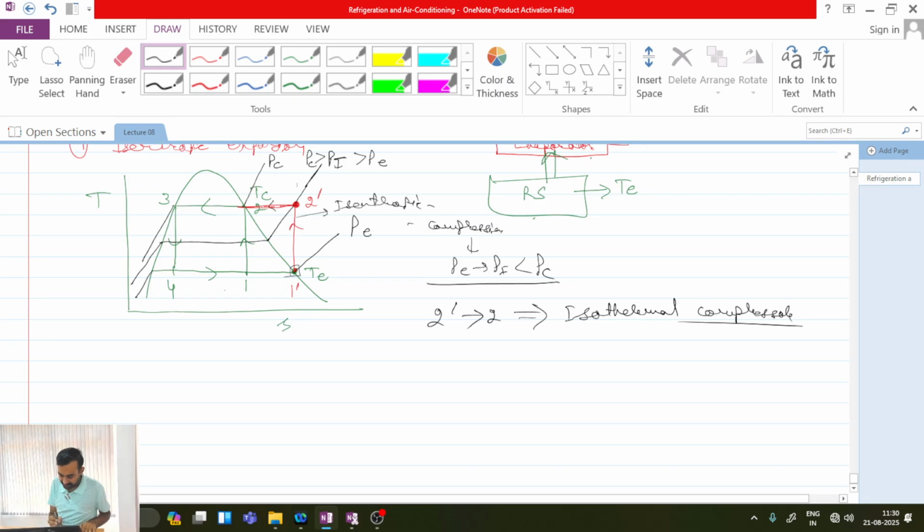The isothermal heat addition and isothermal heat rejection are actually challenging processes because these will either require a large amount of time, which will make the whole cycle slow, or again contradict the isentropic compression, or you require an infinitely large heat exchanger to produce some finite amount of heat transfer. Is this point clear? So these were the limitations which we discussed.